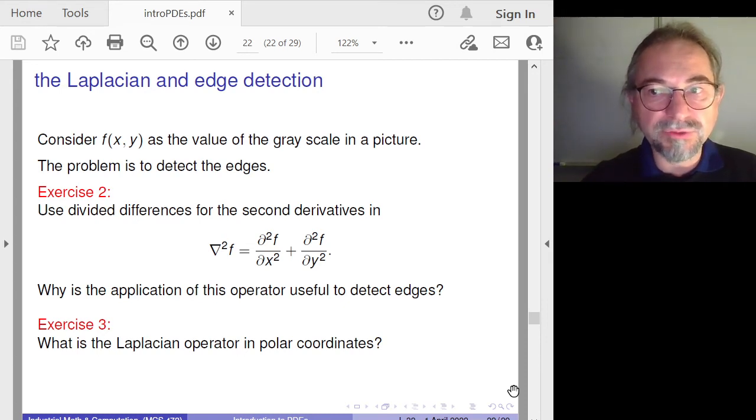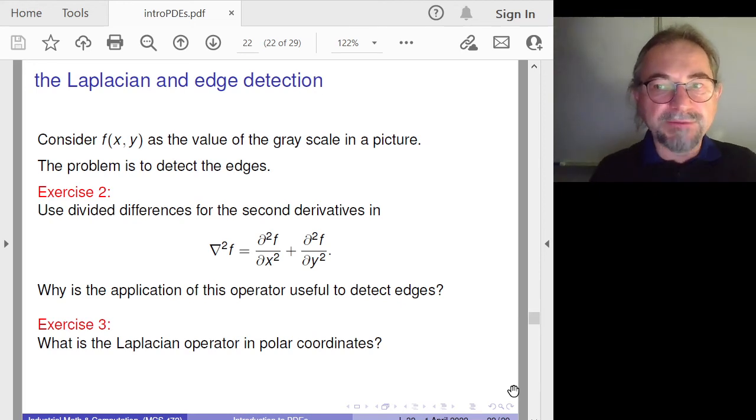what you essentially are doing is averaging, taking the differences between the current point and the neighboring points. We now have our picture as a matrix of grayscales. So if there is an edge, you have regions of the same grayscale and regions of different grayscale.